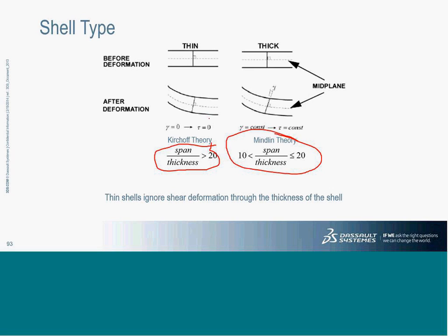Other way around, for any geometry we can safely use thick elements and it should be okay, no issues. However, ensure that we do not neglect comparatively thicker joints which are meshed with shell elements and not use thin elements. Now there is a complex option you will see over there. Unfortunately, that is not part of this training, so I'm skipping it here. If you are attending the nonlinear and dynamic training, that particular option will be covered there.